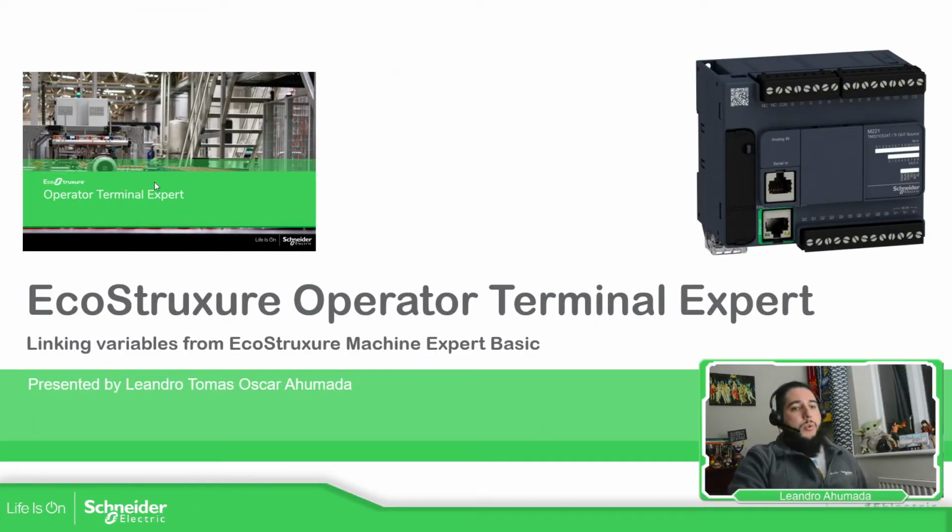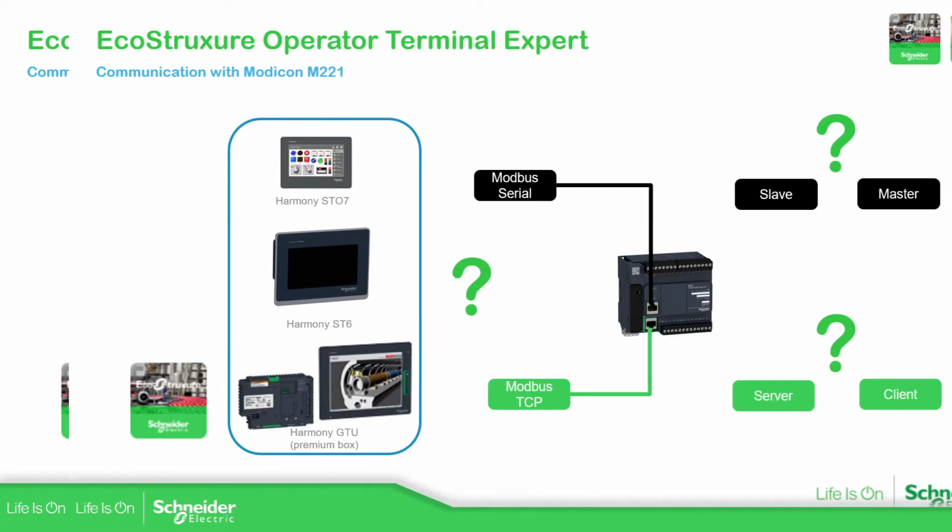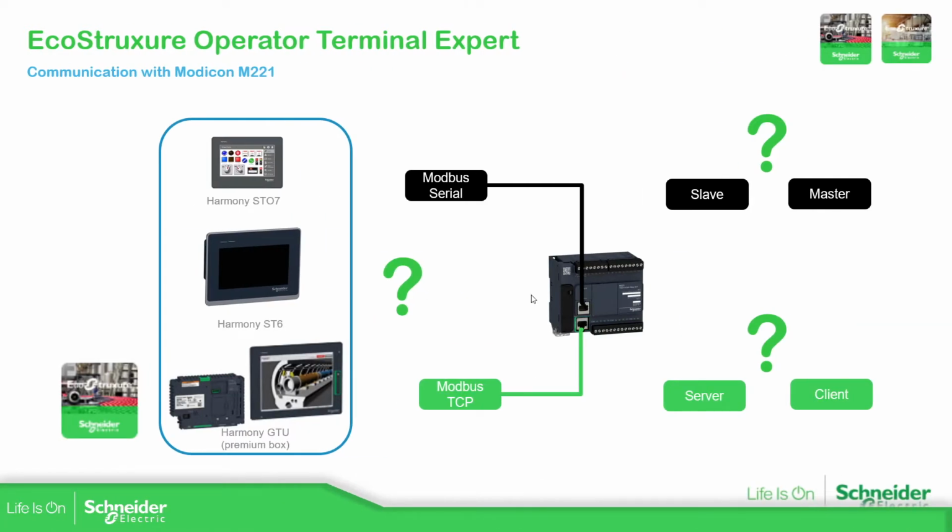In order to communicate the PLC with an HMI, if we're using the Modicon M221, we have two different ways to do it, as I can show you here. We can use the Ethernet port of the M221 or the Modbus serial port that we have. Let me just go full presentation over here. Depending on the M221 that you have, we can have one or two ports, but you get the idea. You can use Modbus TCP as a driver in order to communicate with any of the HMIs inside the EcoStruxure Operator Terminal Expert, or you can use the Modbus serial.